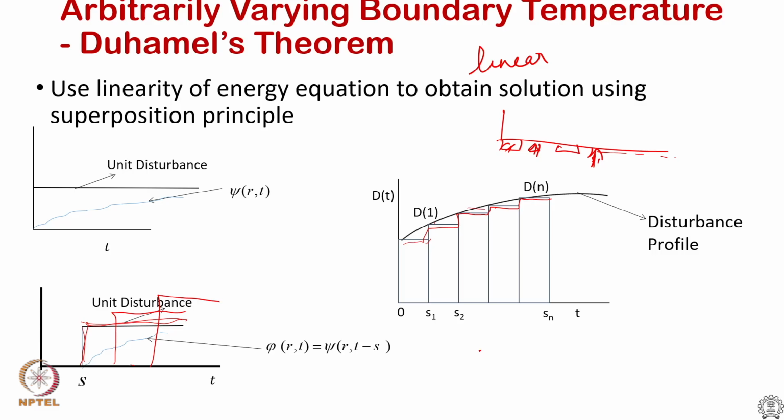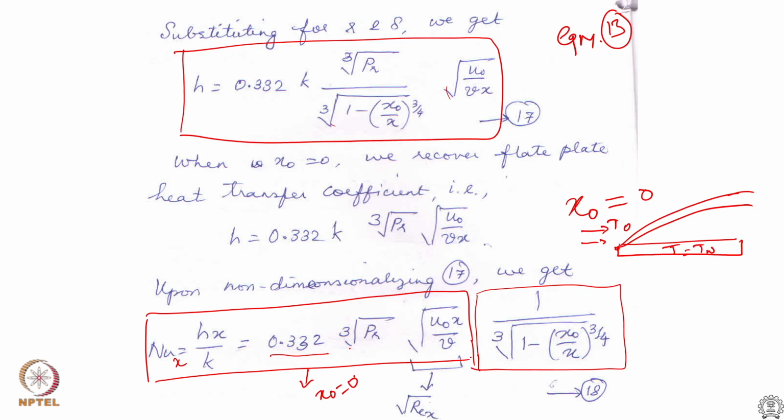Once you get that linear solution superposed, then in the case of arbitrarily varying temperature along the wall, you can easily get the same expression that we have developed previously, and just use an integrand and a summation to obtain a final solution for any degree of variation. That is useful in forthcoming situations that we will discuss. We will not develop the arbitrarily varying solution here, but we will make use of this discussion in the future.